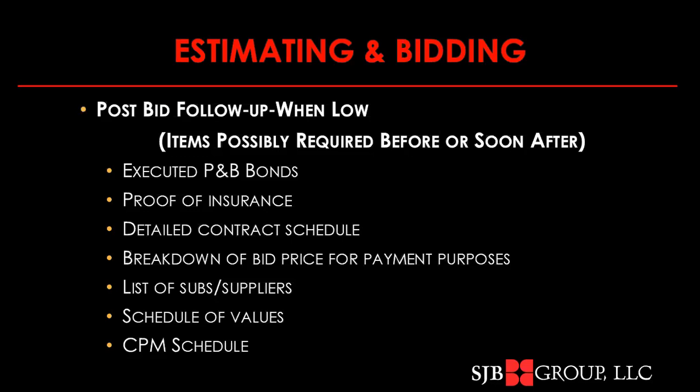If you have a lump sum or a significant lump sum pay item in the project, you may need to start developing a schedule of values. It's fairly common in the vertical construction, where a lot of things are bid as a lump sum, but shortly thereafter, the owner's representative is going to be asking you to break down that lump sum price into parts, and the parts get paid incrementally through the various progress payments.